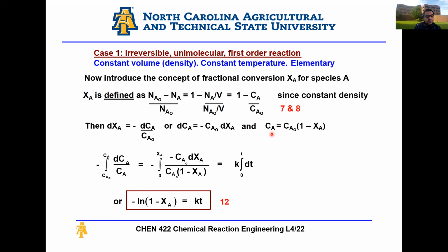Then basically you can always rewrite any expression of concentration in terms of conversion. One point I want to make here is there's a chunk of you who tend to convert everything to conversion when solving a problem. That is fine. However, just be aware that sometimes converting your equations from concentration to conversion might make the math a bit more complex.